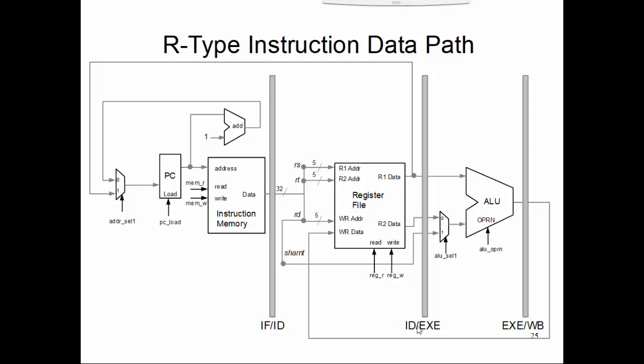So your instruction 2's data goes over for cycle 3, where instruction 2 comes into the register fetch stage at that cycle, and instruction 3 is being fetched from the instruction memory. So that's how data flows from instruction to instruction in a pipeline fashion through these registers.